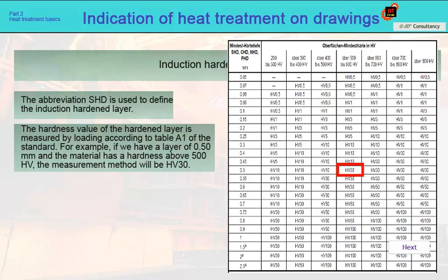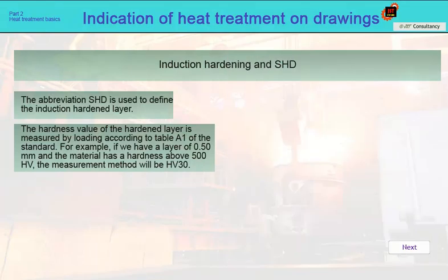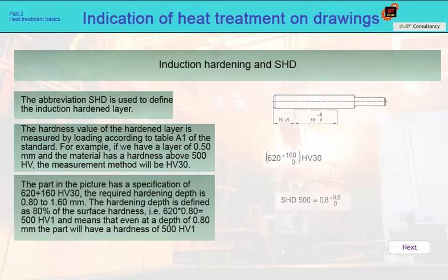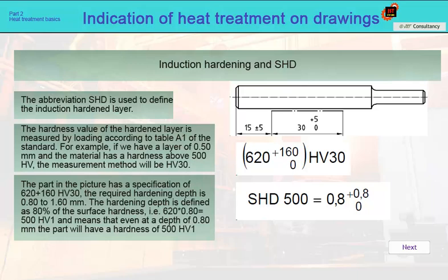The recipe for the quenching depth is always given in the drawing, including the required ultimate hardness, measured according to the Vickers method in HV1. It is assumed that the layer to the specified depth will have a limit hardness, which is usually 80% of the surface hardness. This is even in cases where the surface hardness will be measured in HRC, HRA, or HRN.